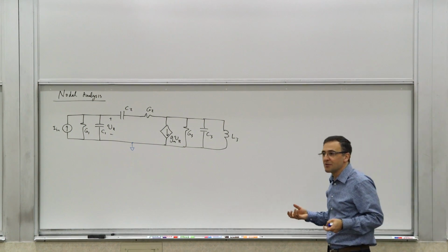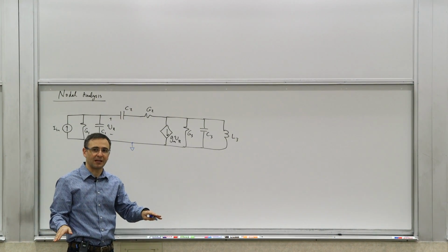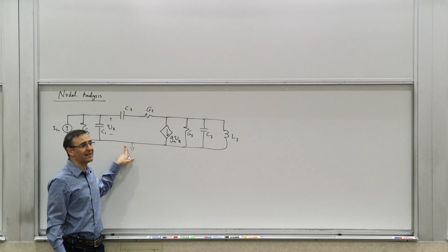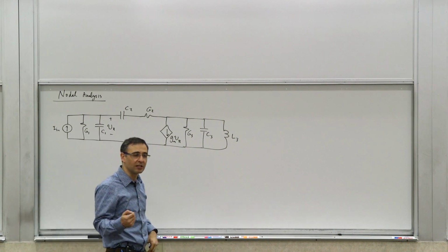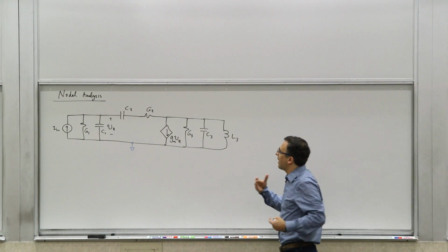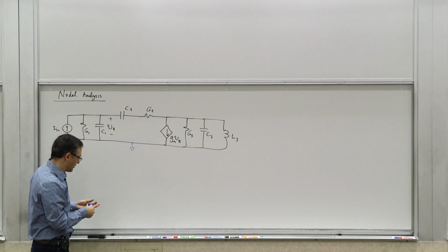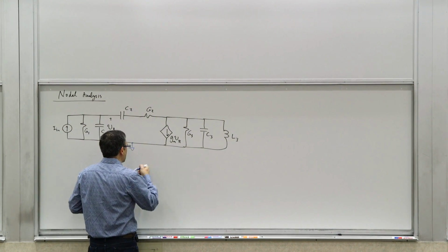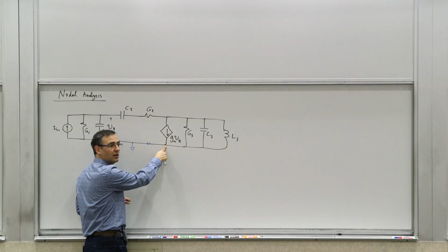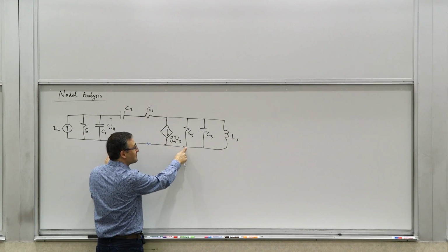Or if you're making a chip, you may have a wire bond connecting this pad to a larger piece of metal and that pad to a larger piece of metal, and you may say all of them are ground. Now, if you assume they're at identical potential, you've made an assumption that can lead to errors, especially at high frequencies, as we'll see. But from a mathematical perspective, this is what it is. In those scenarios, if you have a resistor here and a resistor there, then this becomes a separate node. So you really treat this as a separate node. And if there's a resistance intervening between these, this becomes a separate node.